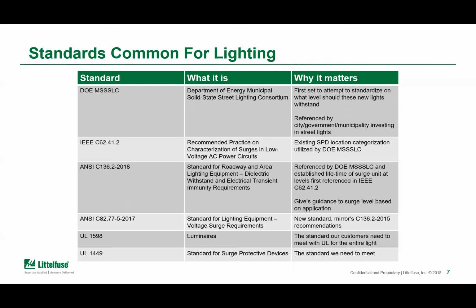IEEE C62, which is the one I've talked about quite a bit already, essentially provides recommendations on evaluating low voltage AC equipment, which essentially means anything under 1,000 volts, to transient threats.